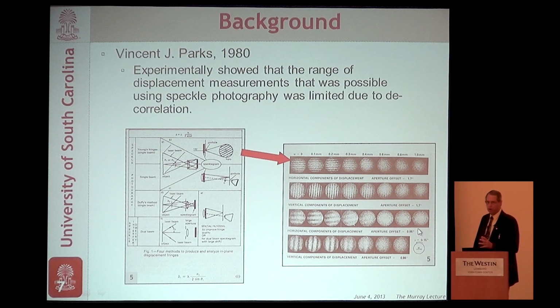Here, if you move too far, you rotate too much, and it's all small deformation, you lose coherence of the laser speckle pattern. As a result of that, when you try to reconstruct the deformations, it doesn't work. Before that, of course, it's fine, but all of that required that you be careful about your deformations, and large deformations, including out-of-plane deformations, simply weren't tolerable.